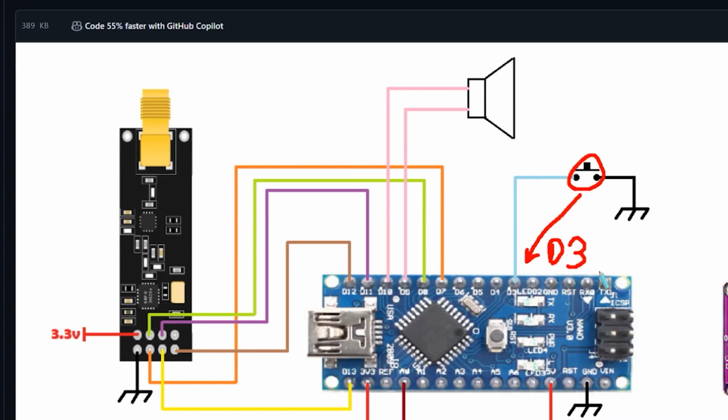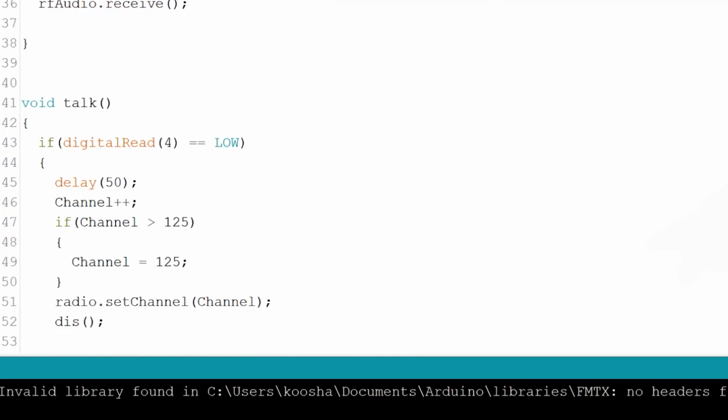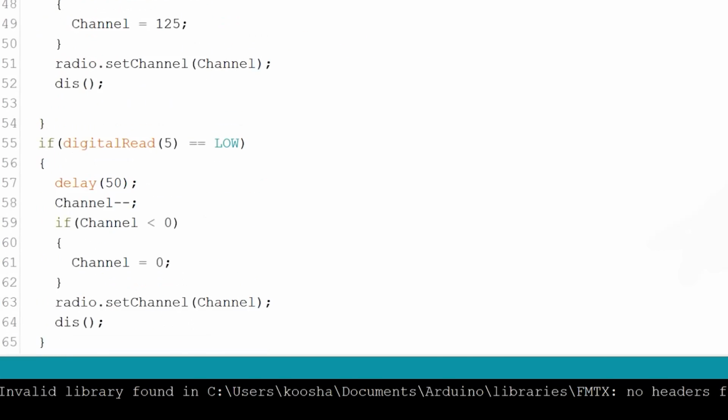When the microcontroller is very busy processing something, only with the help of the interrupt function can the execution of the main program be temporarily stopped to execute another program. Apparently, this is what we have to do, so I wrote instructions that if the interrupt pin changes state, the communication channel changes. But this requires a side circuit.